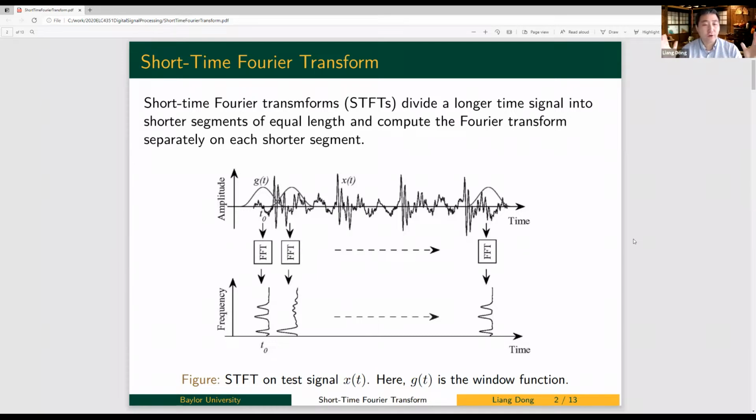You have to wait for a long time and collect all these signals and do it in one shot with a Fourier transform. The other problem is that if you are going to collect the entire signal, you cannot guarantee the frequency will not change. If it's a static signal, I can collect it thinking that the frequency component does not change, and calculate the Fourier transform. But the chances are that the signal is going to change.